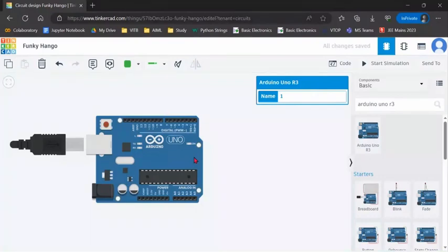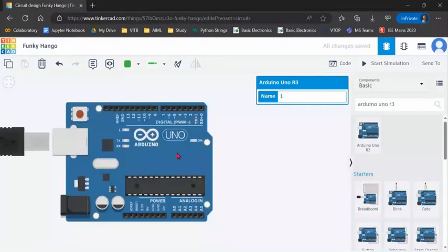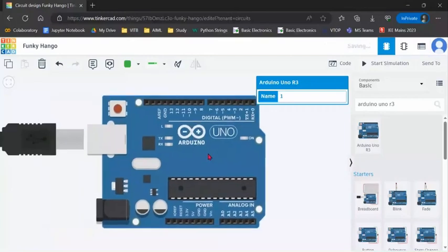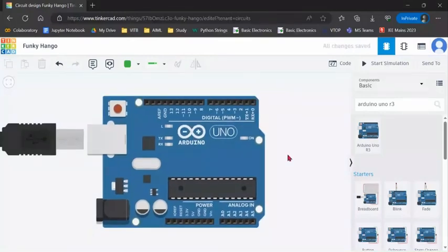So here, I hope it is visible to everyone. In this Arduino Uno, this is basically the microcontroller that does the decision making based on the input provided to it. Here this will be a reset pin. Whatever programs we have burned or written inside this microcontroller, we can reset it, and whatever program it had been programmed with previously will be deleted. This is where we should provide the power supply separately, or we can use the USB directly to provide power.